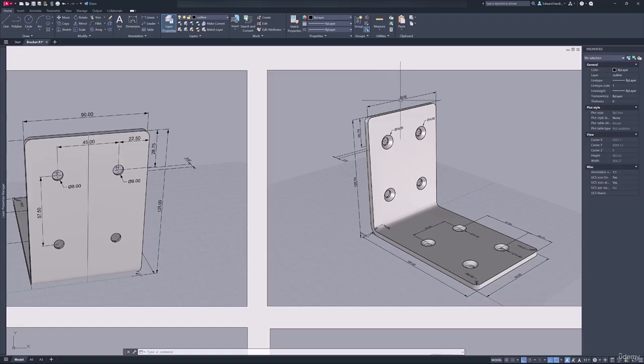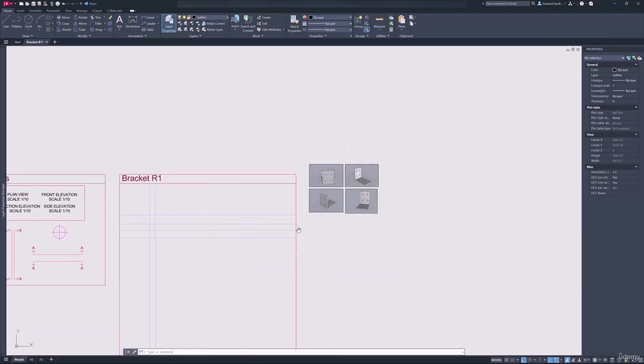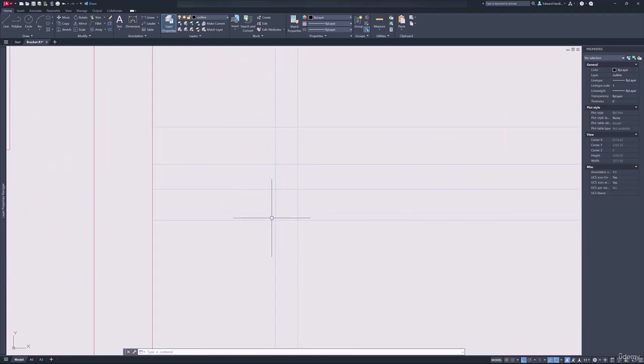So what can we tell? We can see that it's 90 millimeters wide by 125 millimeters. So let's go ahead and do that first, and we're going to do it in this one here. So go ahead and start typing in rectangle. So I'll just press RE and then I'll select rectangle.